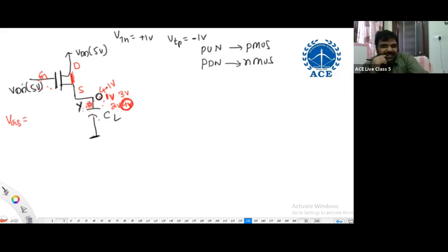I'm expecting a logic 1 which is a strong one, because this may be used as input of another logic gate. So again, it is becoming slow because the gate potential is not 5 volts for logic 1 now. It is 4 volts. Further, if you are taking one more stage, it may become 3. It may become some other volts. So logic 1 may become logic 0 after some cycles, after some stages. It is a problem that should be eliminated.